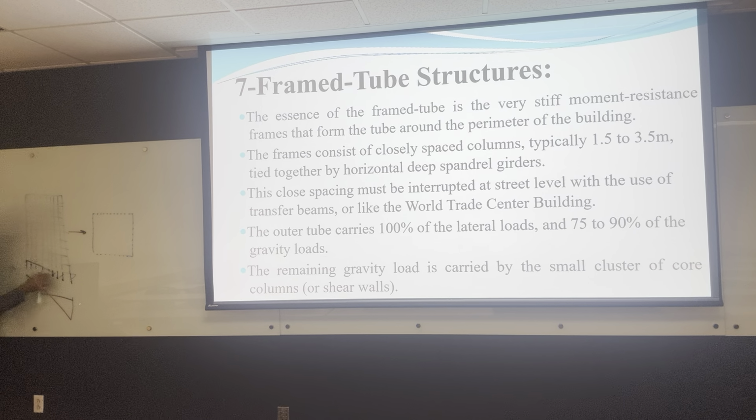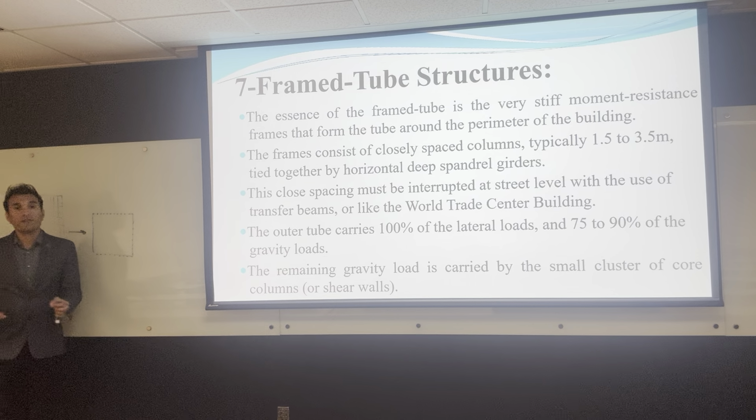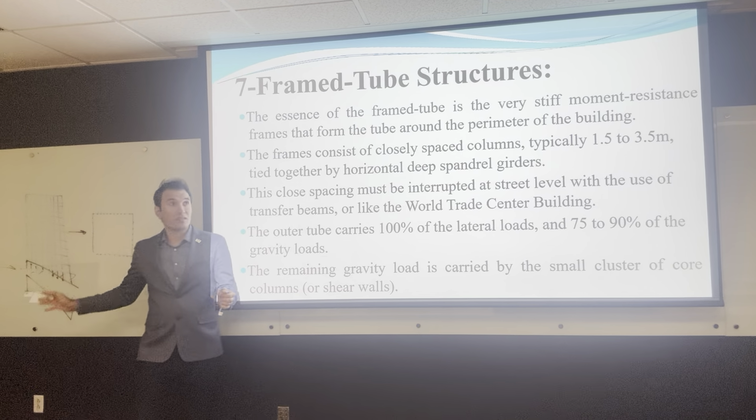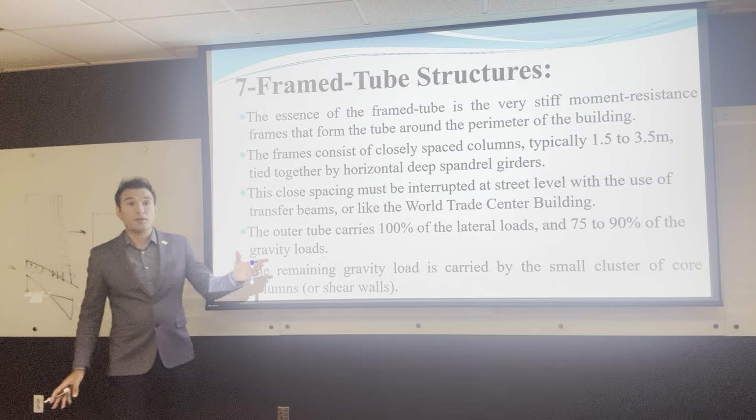So the stresses are gonna be something like this. Basically the columns are acting as a shear wall, but there's only one downside of the shear wall. It's not a solid shear wall, so it's not a perfect shear wall. So there's a phenomenon that happens in the frame-tube system. Actually, it's called the tube system, frame-tube system.